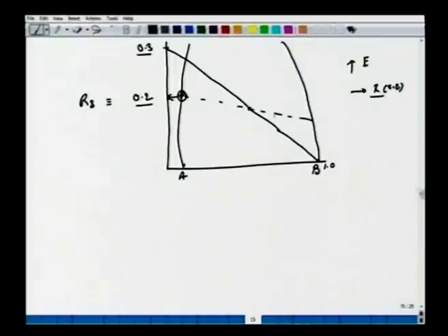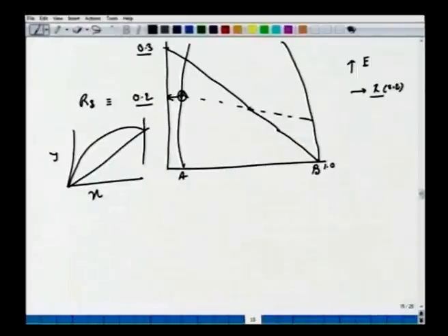So if you do this, you have the equilibrium Y versus X diagram from the same information we had in the beginning of this exercise. You have to look for point 2 here, corresponding to this, and find out the composition in the y phase. If this is point 2 here, you find this tie line, and you will see that this corresponds to 0.078. So actually here this is now x and this is your y.